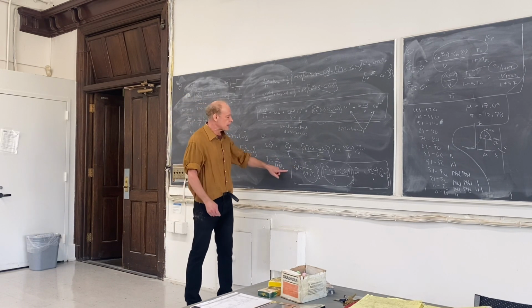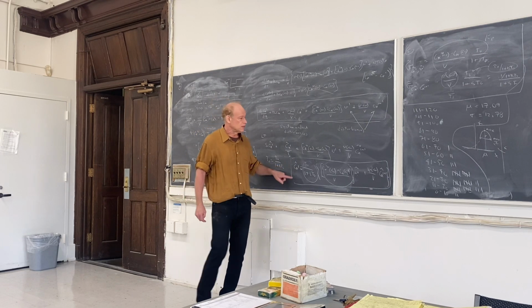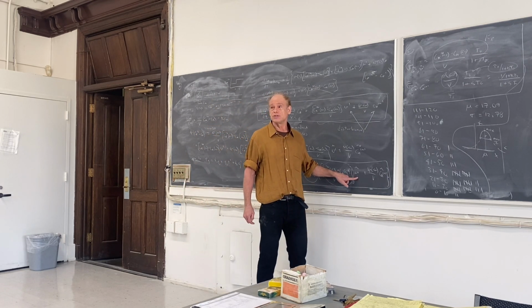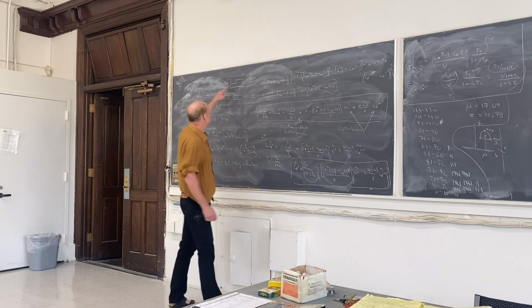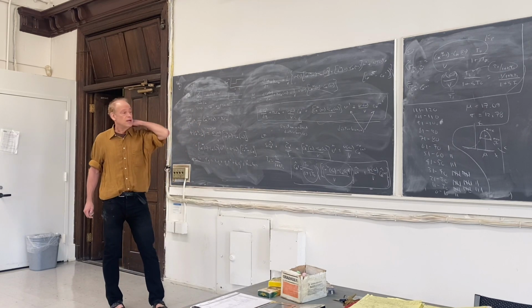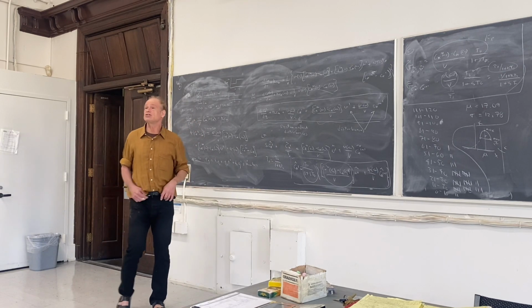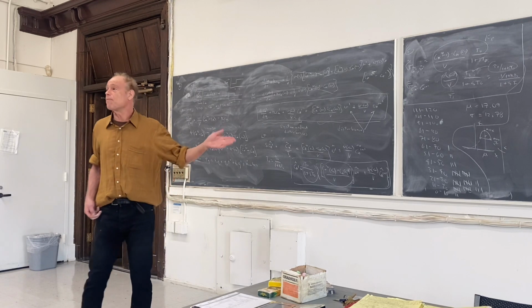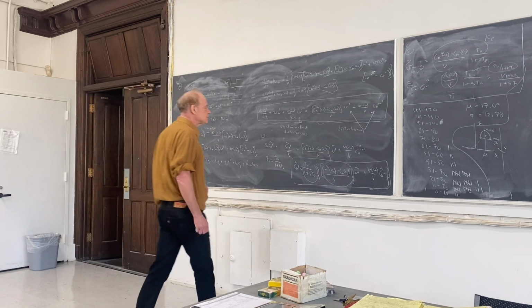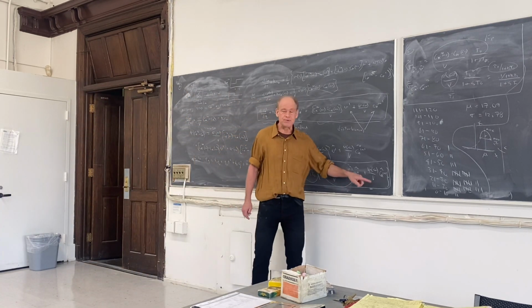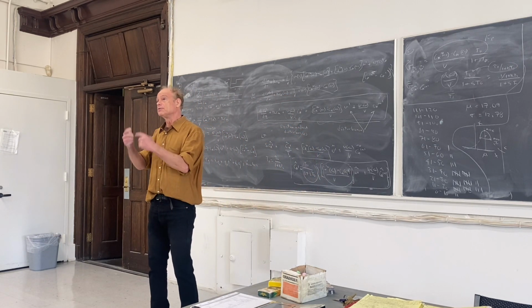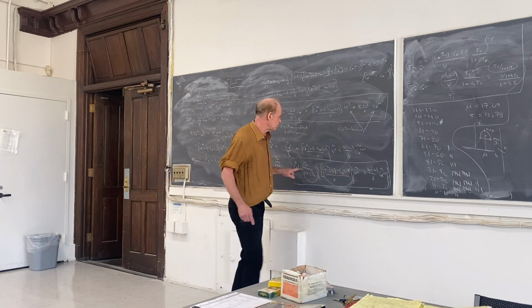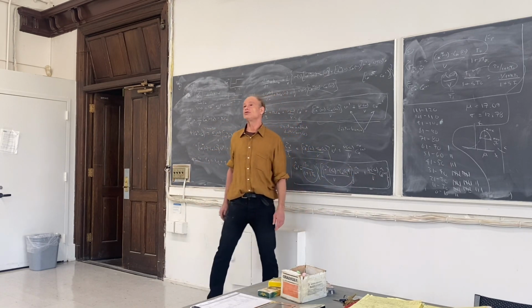And notice this is the output, Ca prime tilde, and there were two inputs that were changing, V prime and Ca in prime, because both of them changed at t equals 0. So that tells me, remember, I have a transfer function, and these are all prime variables. So that tells me I have one output and two inputs. So that means I have two combinations of output and input. This guy and this guy, or this guy and this guy. So I've got two transfer functions.